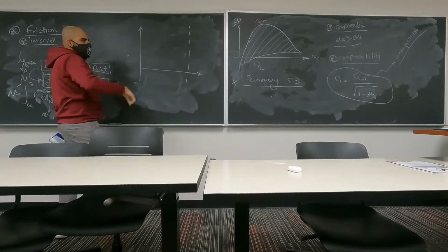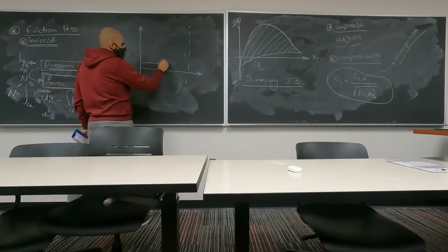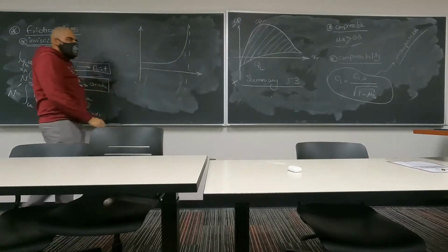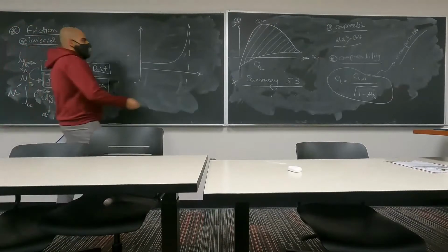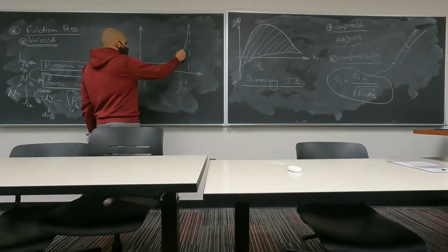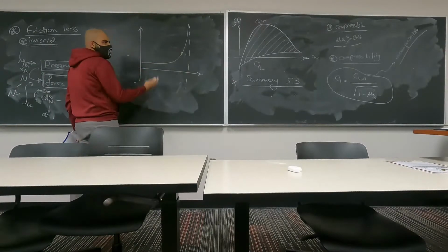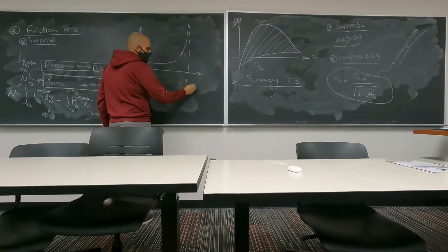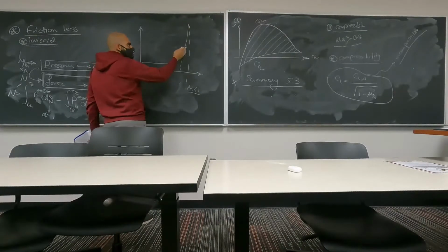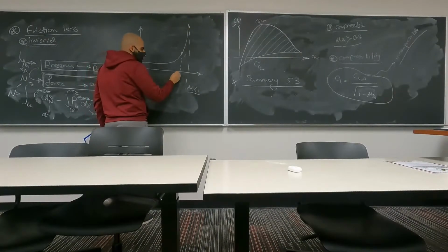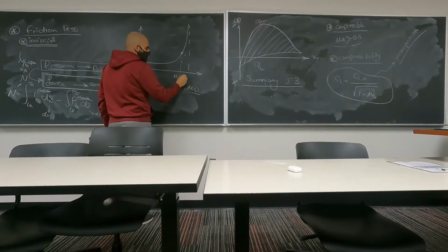So what is going to happen if you do this correction? What's going to happen is going to be this. It will approach infinity as you increase the Mach number, your lift coefficient. But at these values and these regions, you are seeing a huge rise. So it's not just Mach numbers that have to be smaller than 1. It's also Mach numbers before this huge rise, right? Because after this, you're essentially introducing very unphysical corrections.